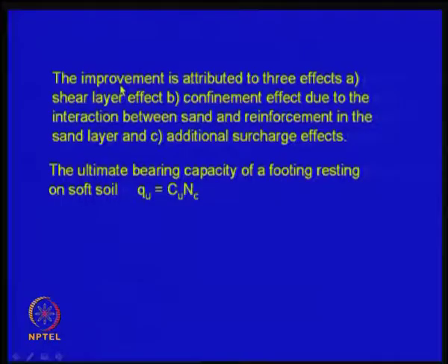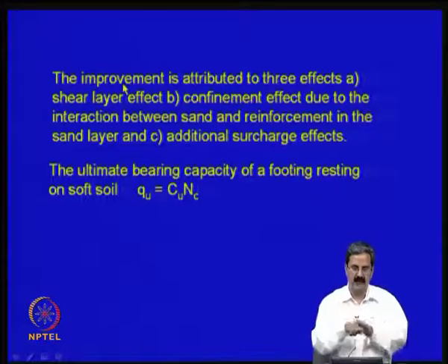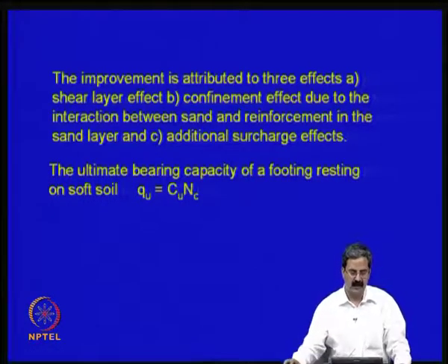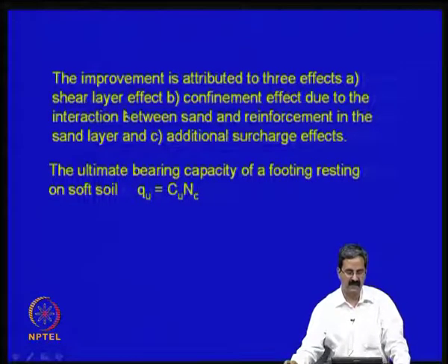As I said, the understanding of mechanisms is very important, because you should know how to calculate. You assume some mechanism, then the mechanism gives you the method of calculation, right. So we can improve the soft soil bearing capacity, and we put some sand layer and also put some reinforcement in between, and we say that there are 3 effects that will help us.